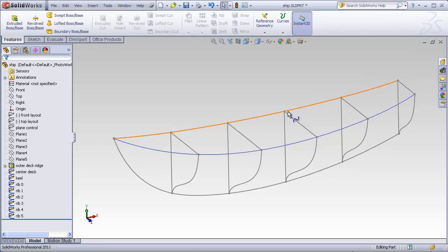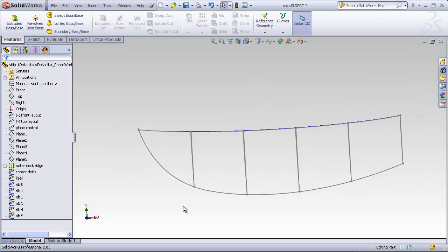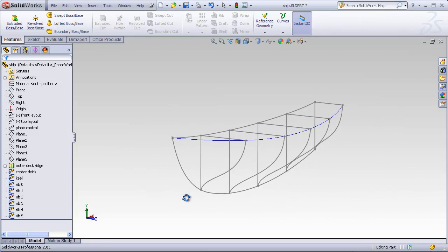If you try to draw the guide curves to conform to the profiles, you're probably going to have the same kind of problem you have if you make a spline with too many points. The chances are that you're going to get a little wave or lump in your guide curves, which is undesirable. Also, the guide curves should be doing exactly what their name suggests. They should be guiding the overall shape of the object you are trying to create.